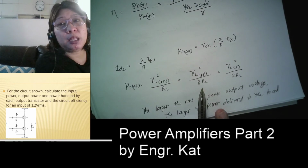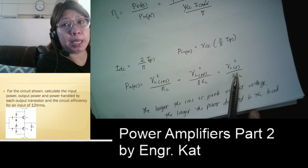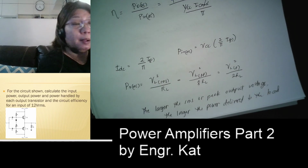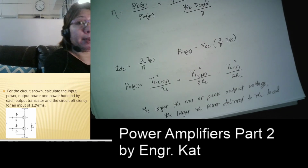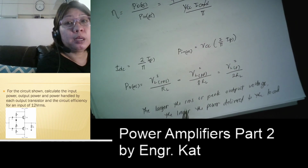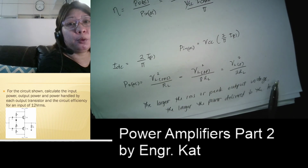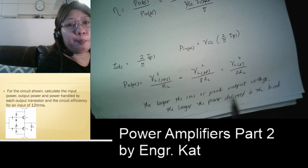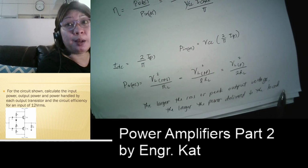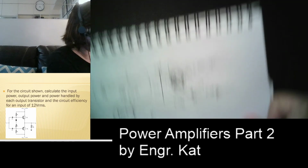And if that is in terms of peak voltage, that is equivalent to VL peak squared divided by 2 RL. So the larger the RMS or peak output voltage, the larger the power that is delivered to the load, of course. It is directly proportional.